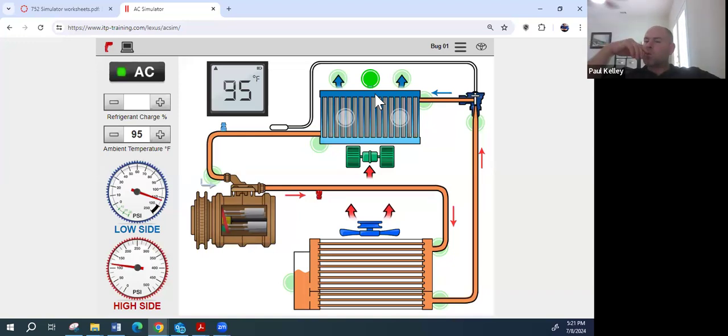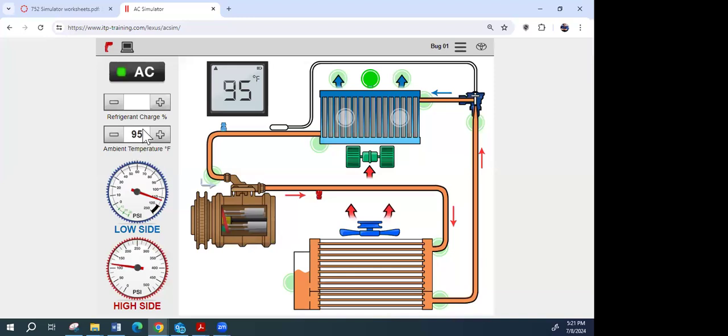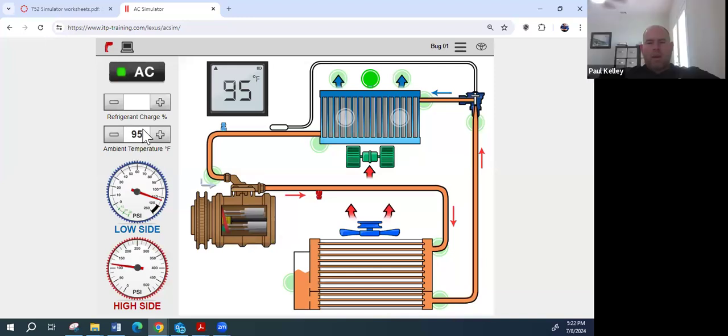Is there a better term we could use? What's the temperature outside? Do you remember? Ambient temperature. Yeah, I agree. It's blowing ambient. So as soon as a car is blowing ambient, that should put your brain in a mode of like, okay, I don't think the AC is working at all.